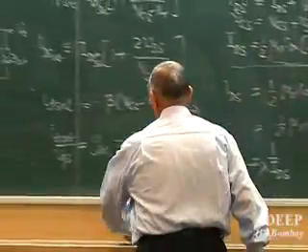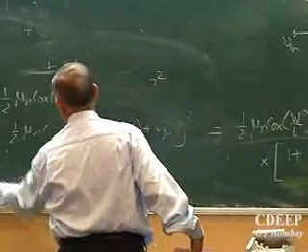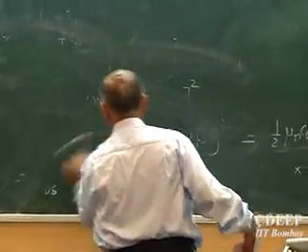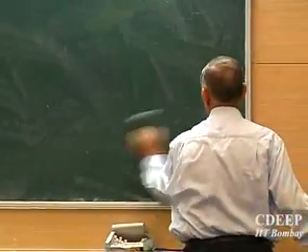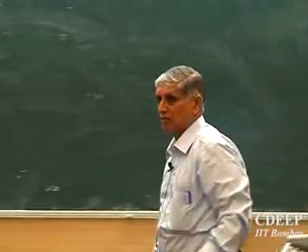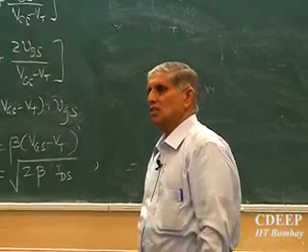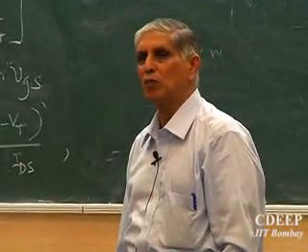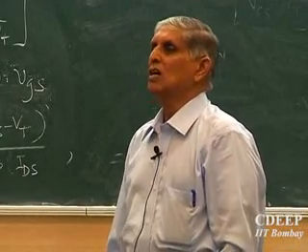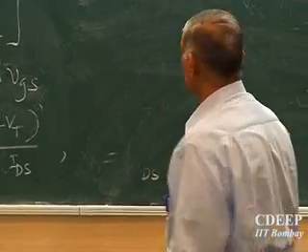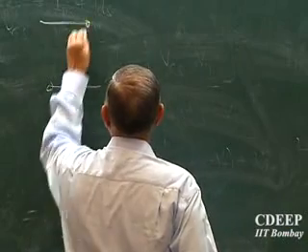I am using certain frequencies in which all capacitance can be neglected. What does that mean? If I say I am having frequencies in which all capacitance effects are neglected, what should be the frequency order? The impedances become dominant at high frequencies, so right now assume low frequency small signal analysis, and in that case the equivalent circuit will look something like this.